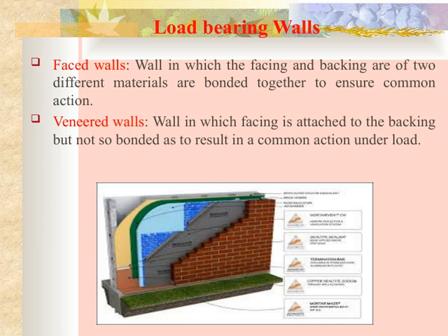Now, moving on to veneered walls. In these walls, the facing is attached to the backing, but there's no strong bonding to make them act together structurally. Think of it more like a decorative layer that's attached for appearance, but it doesn't contribute to the structural load-bearing capacity. Understanding these distinctions is important because it influences how we design and construct walls to ensure they perform safely and efficiently under various loads. Recognizing whether a wall is faced or veneered helps us determine its load-bearing capability and how it fits into the